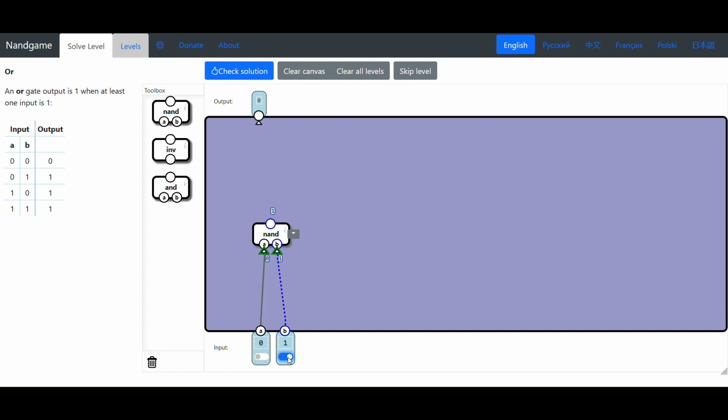And every situation, or every combination of inputs except for when both of these inputs are on, the output will be on as well. It's only when both inputs are on that the output is off. And we can see that this is pretty much the exact opposite condition with our OR gate. For instance, if we were to take these input values in this table here and just invert them, we would have the same behavior as our NAND gate.